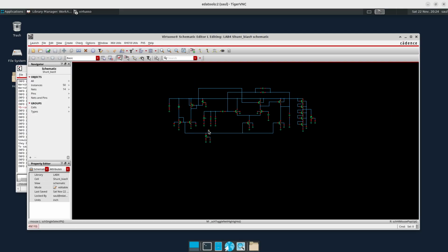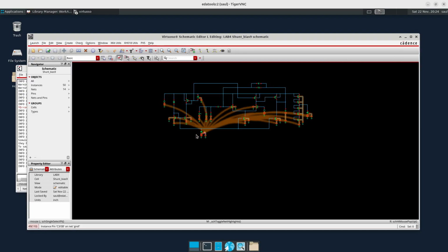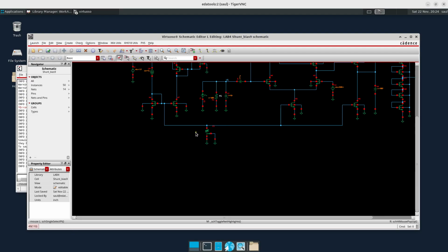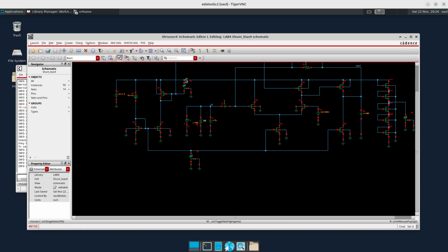That is a very important detail. These coupling capacitors also help me to filter high frequency noise. So there may be noise coming from the current reference here, and then I am building a low pass filter also with this capacitor. The same here. Remember that the current mirror is extremely noisy, so I can benefit from the presence of these capacitors because they act as low pass filters.